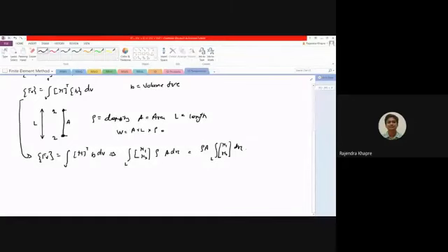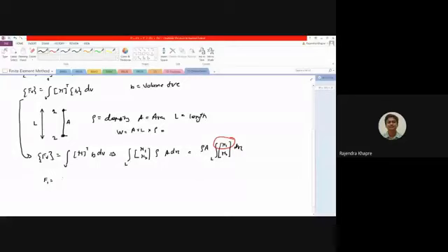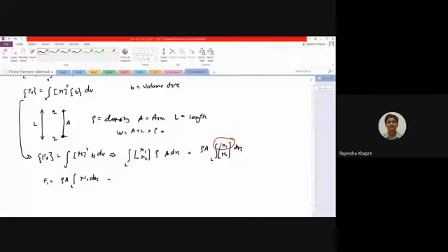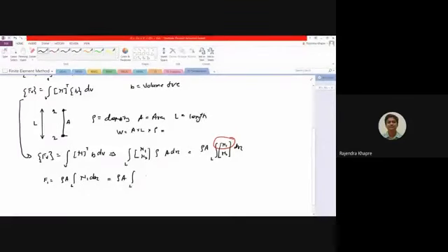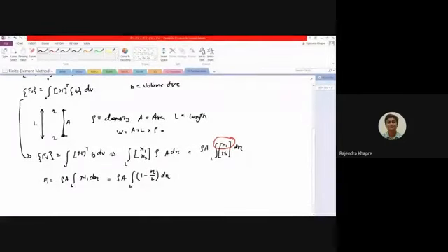So now if you go for the first part, I am highlighting the first part over here. This is my first part. So if I take the first element of the force matrix, let us call this F1. So F1 now can be rewritten as rho into A, integration over the length, into N1 into dx. If you remember, the shape function of node 1 is 1 minus x upon L over dx, isn't it?